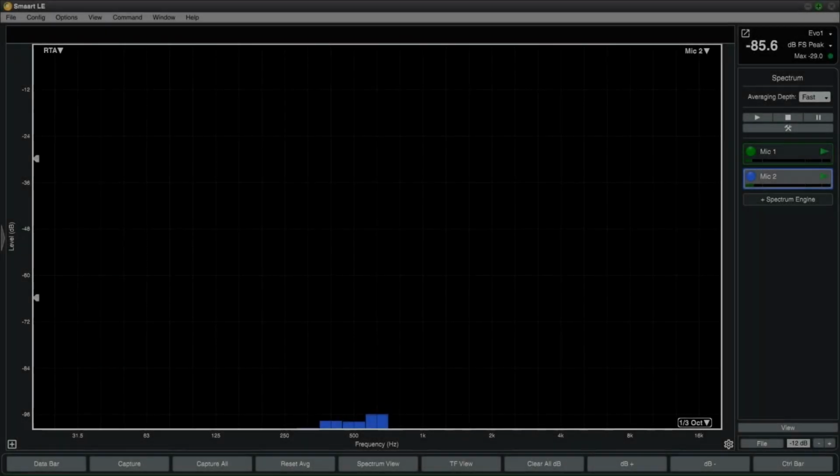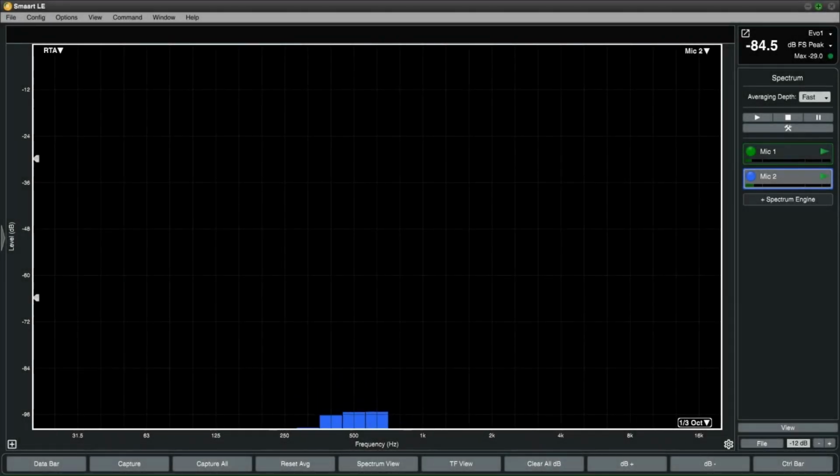All versions of Smaart have a calibration tool to display the input signal in SPL values. You will notice that the top right SPL meter is displaying dB full scale reading. In this case, all values are negative, and 0 dB is the clip limit of your system. Any other metrics, such as SPL A-weighted slow, are grayed out. This is because the input selected has not been calibrated.